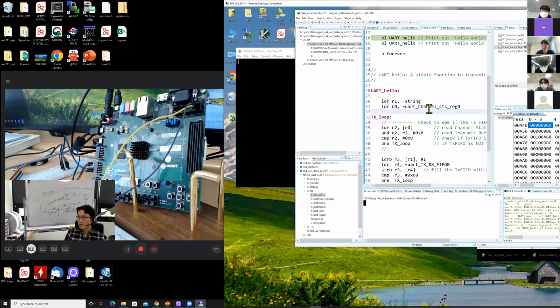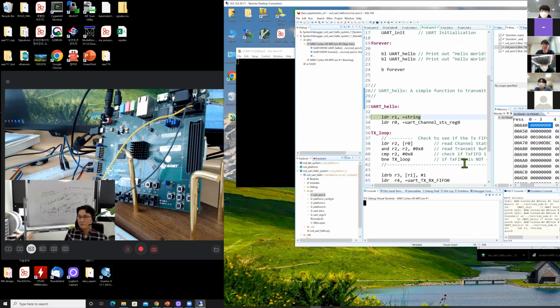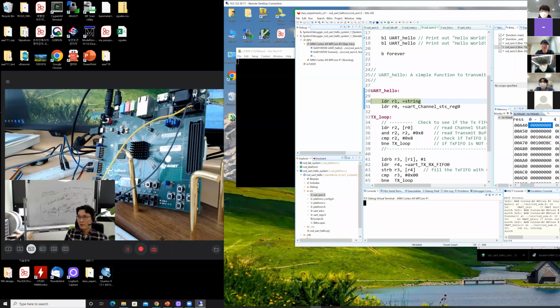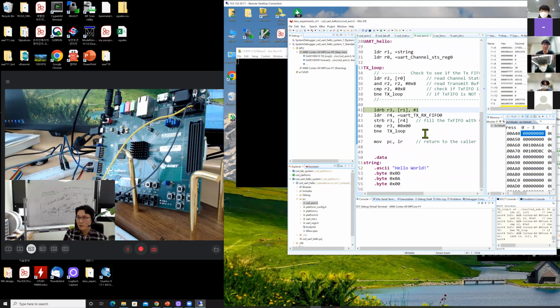From here I want to check out this code, line by line, instruction by instruction. So press F5. Okay, so then F5, right? It is checking some status register to see if everything is okay. So for now, let me just execute it. So now it is reading the R1 location.